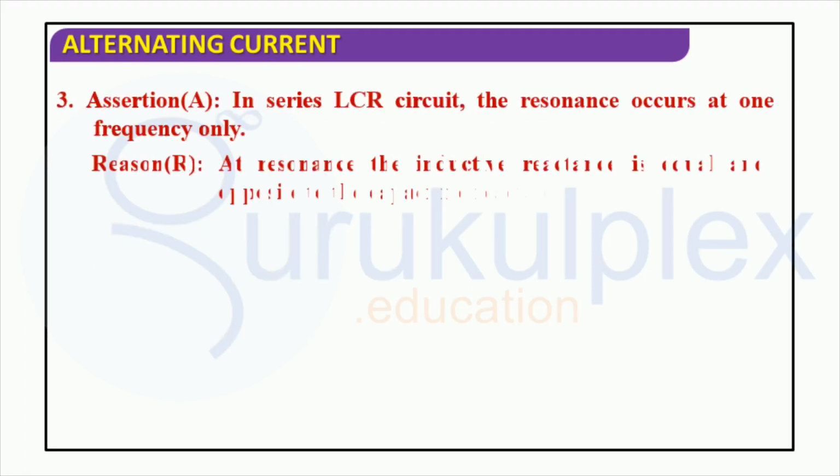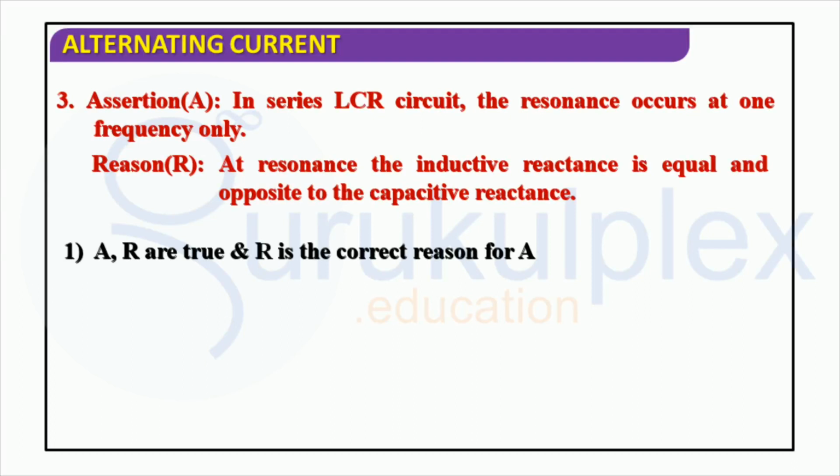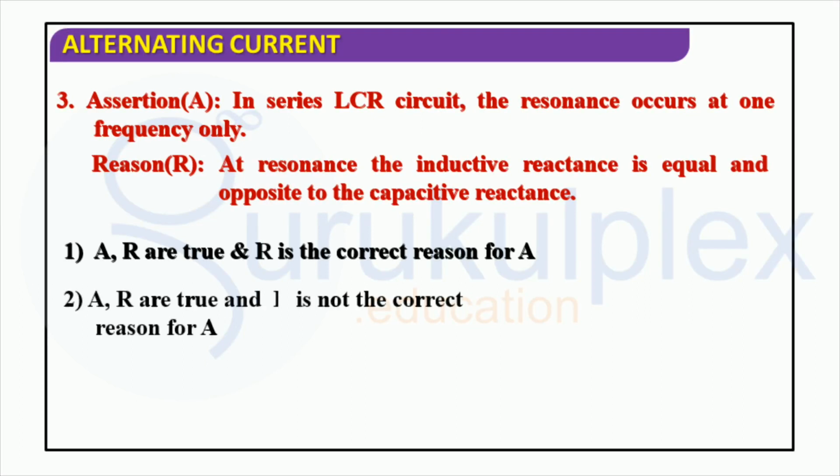In series LCR circuits, resonance is observed at one frequency due to the fact that when inductive reactance and capacitive reactance are equal in magnitude and opposite in sign, the net reactance equals 0 and the current attains its maximum for that specific frequency.